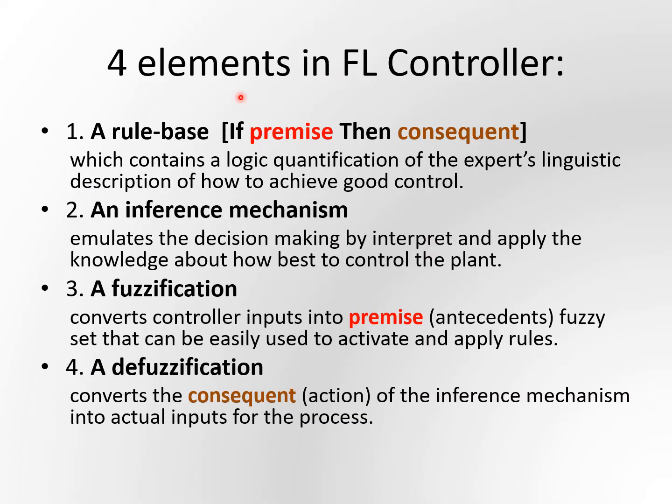There are four elements in the fuzzy logic controller. One is the rule base, premise, then consequent, which contains the logic quantification of the expert's linguistic description of how to achieve good control. The inference mechanism emulates decision making by interpreting and applying the knowledge about how best to control the plant. The fuzzification process converts the inputs into antecedent fuzzy sets that can be used to activate and apply rules, and the defuzzification converts the action of the inference mechanism into actual inputs for the process. So these are the four elements that we have mentioned before.